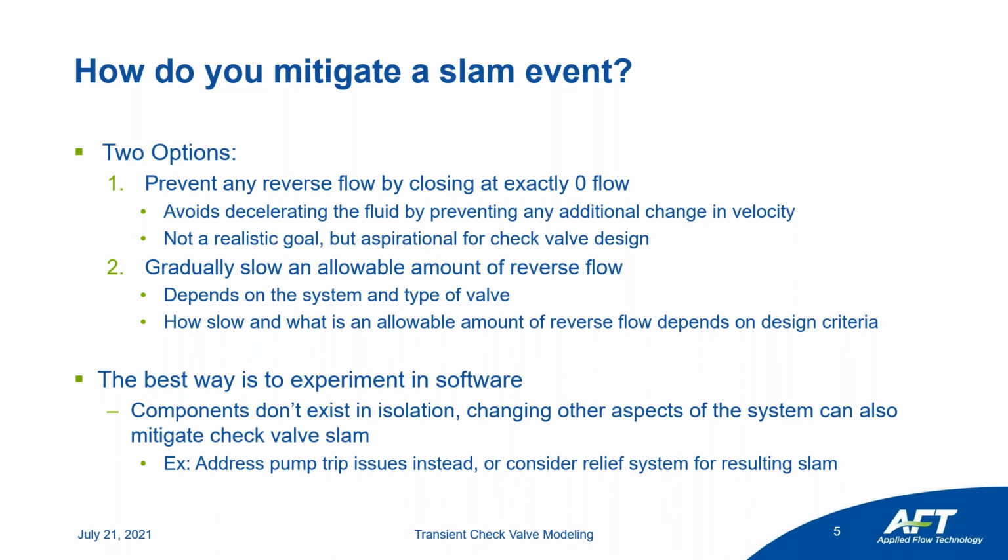So while there may be an issue with check valve slam, you don't necessarily have to address that issue at the check valve. If the check valve slam is caused by a pump trip, there's other ways that you can make a pump trip longer, so that way it isn't decelerating the fluid as aggressively, and that check valve doesn't have to suddenly look at super high flow and all of a sudden change to no flow and slam closed.